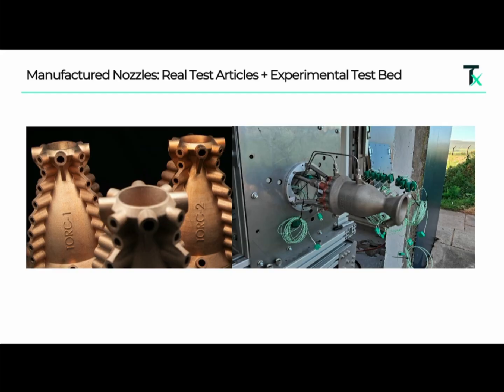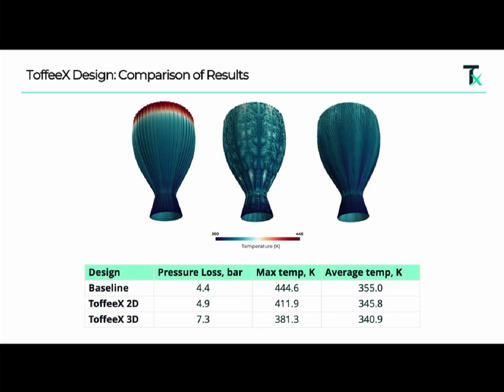But that was a relatively successful project. And in terms of challenging biases, one of the things we were expecting, you can't see it. All right, so basically the highest heat fluxes are at the neck, the throat of the nozzle. And so we would expect a higher heat transfer surface area, more fins built in that region. What we found was this wasn't true. It was building very few fins in that region and loads of fins at the end. So many small features there.